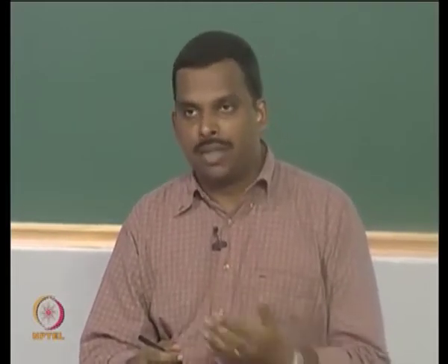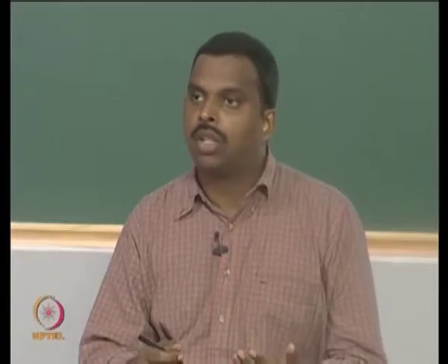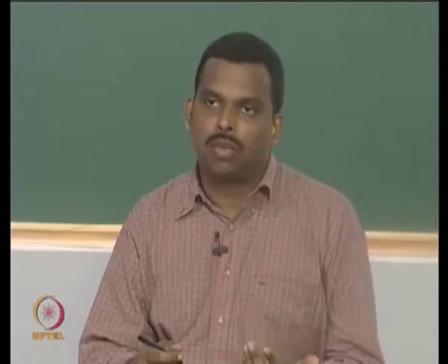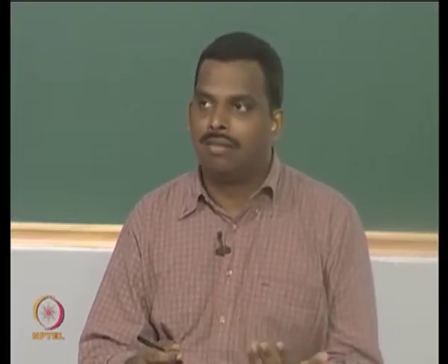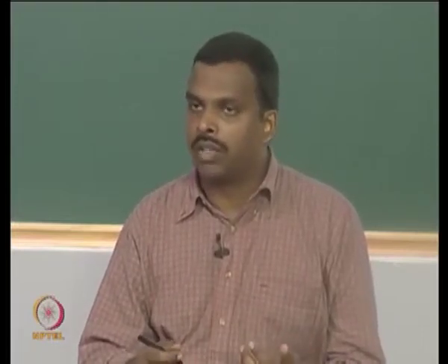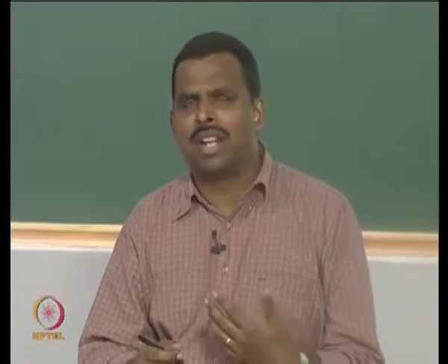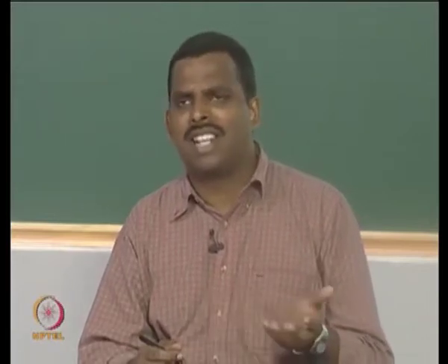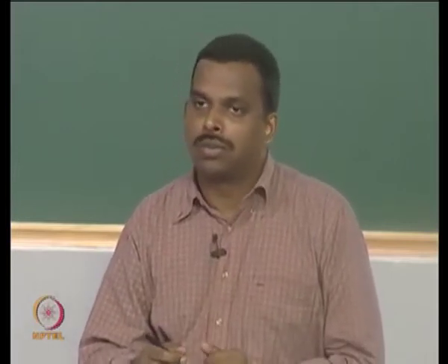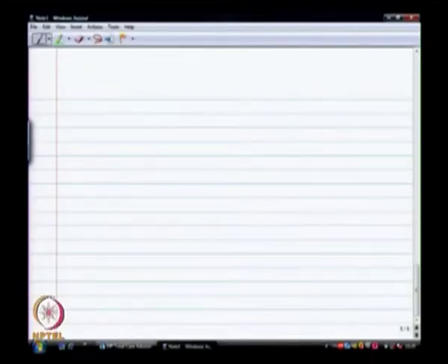And we see that encoding is very easy, you have a shift register circuit. Decoding is also equally easy. You only do computations with a small lookup table, which is very trivially implementable today. So today Reed-Solomon codes are everywhere. Any place you imagine, you have Reed-Solomon codes. So they are very popular, and they deserve their place also.